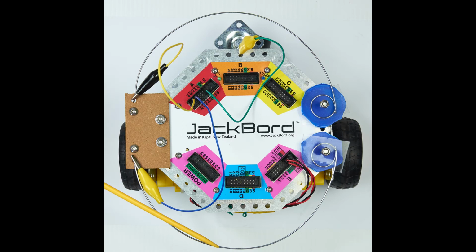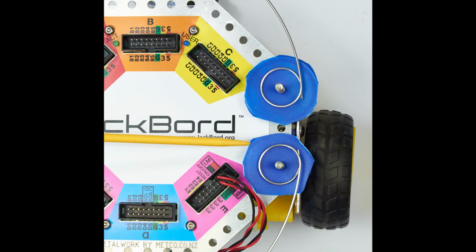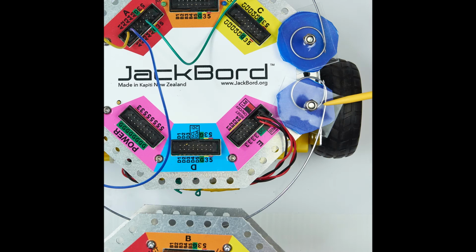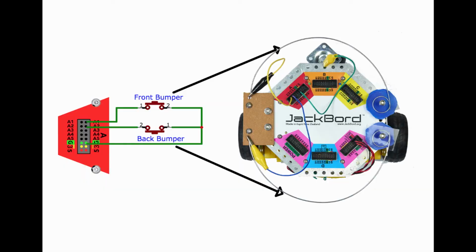The second switch, which is connected to A2, is connected to the rear bumper. And likewise, when the robot collides with something in the rear, this switch is activated. This picture shows the overall relationship between the bumper switches and the port pins on port A.